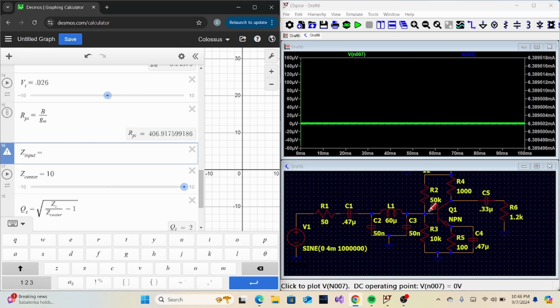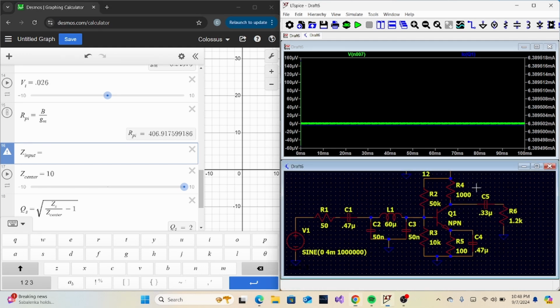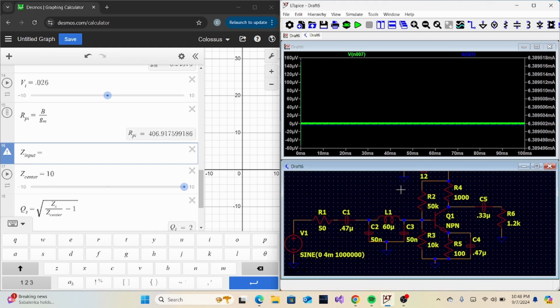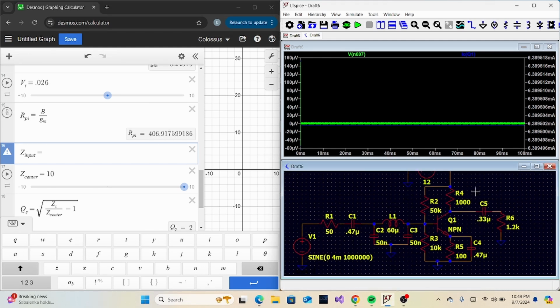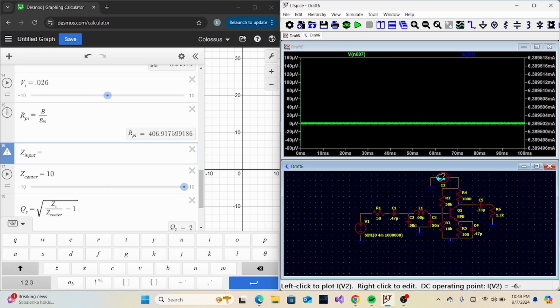And what it'll be equal to is, if you remember, I'm sure you've heard this before, with an AC signal, a DC power supply basically looks like a dead short to it. Reason being is that if this is a power supply, there's going to be a large filter capacitor present between the positive and ground, and the AC signal sees that as a dead short. So we need to short this out when we're thinking about AC and just pretend that there's a ground right here.